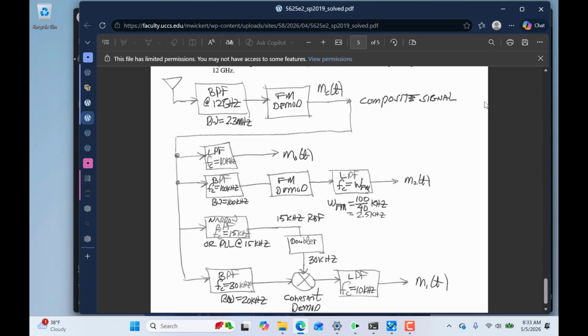I could say, give me 2 ideas about how you'd FM demodulate. And to me, tops on your list would be a traditional analog discriminator, or maybe a DSP-based discriminator, or it could be a phase lock loop. Those are the two types we talked about in class, right? Both can work, with differing amounts of complexity.